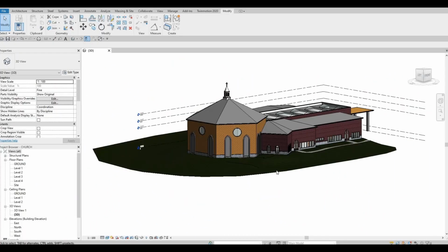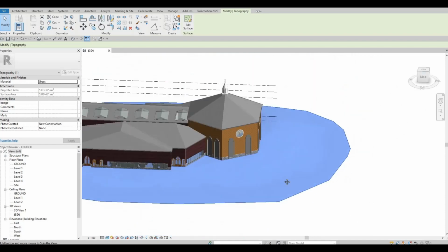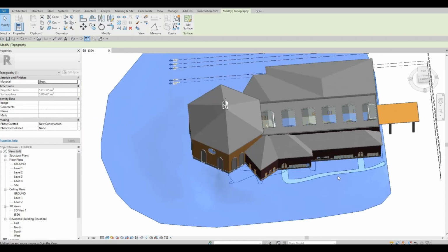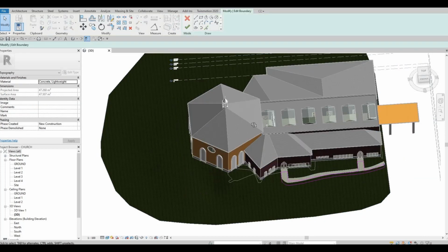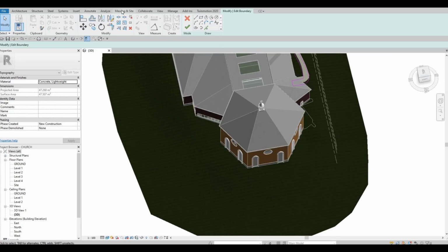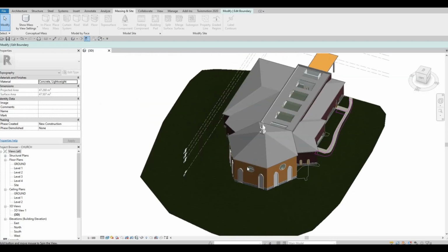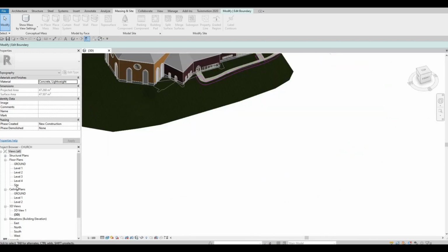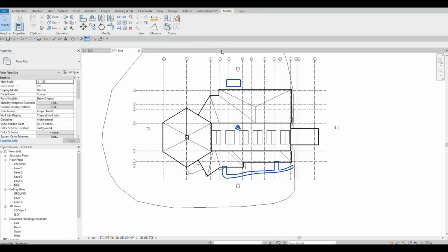So in the previous video, you were able to start adding this. This is the topo surface. Now we're gonna continue working on this, and I'm going to add some of these boundary lines that are the split face with a different material. So I just want to check here underside if I'm able to create another one without even having this. So it looks like I can.